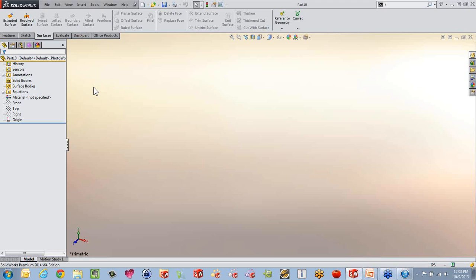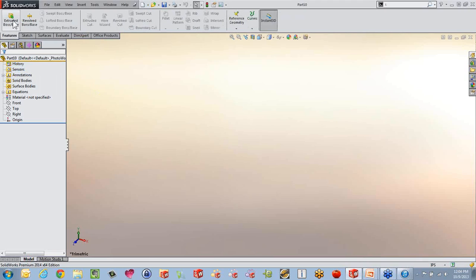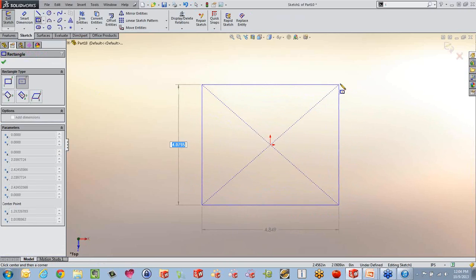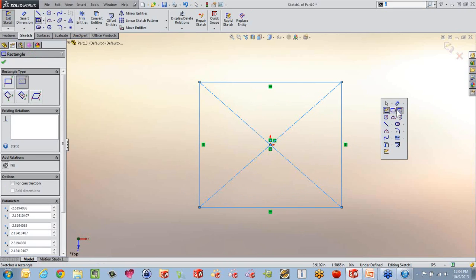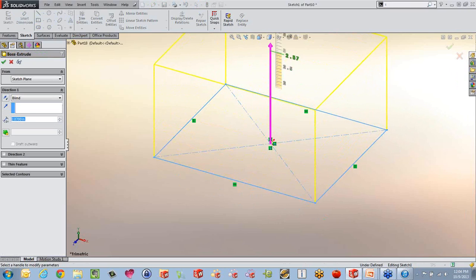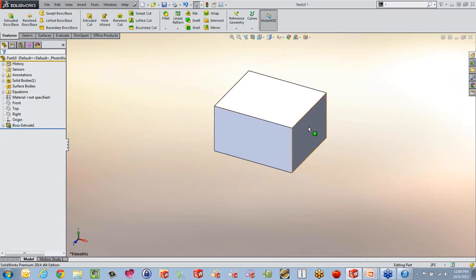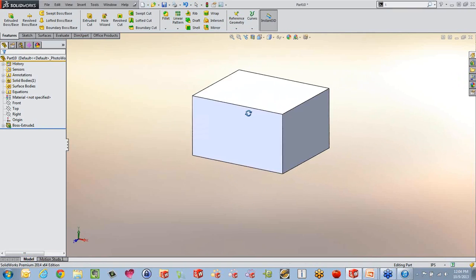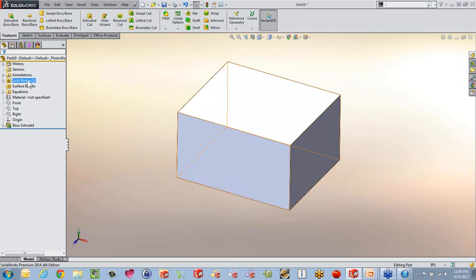So to start at ground zero, with the basic things, if I go into SOLIDWORKS here to a standard extrude and just open up a sketch, I'm just going to use my S key, put in a sketch and extrude this sketch out. This should be all pretty familiar to all of us, I hope, right? So now we have a boss extrude here. This is what we call a solid body, and the solid body is sitting right up here.